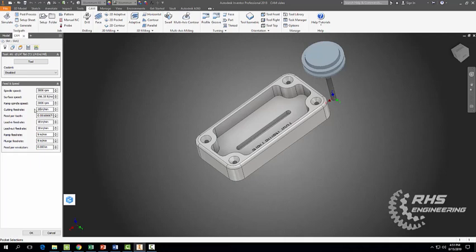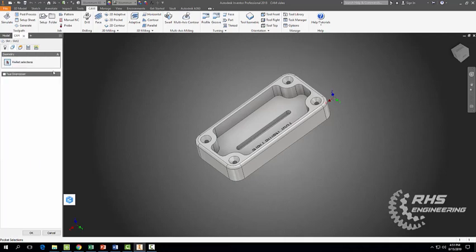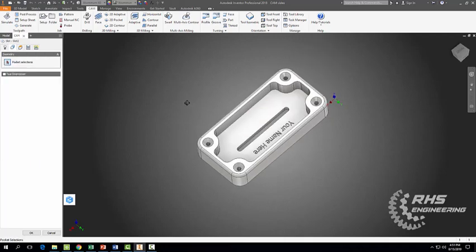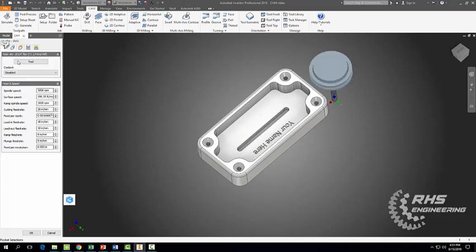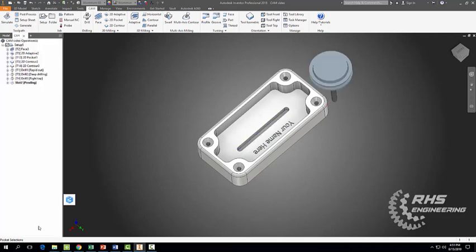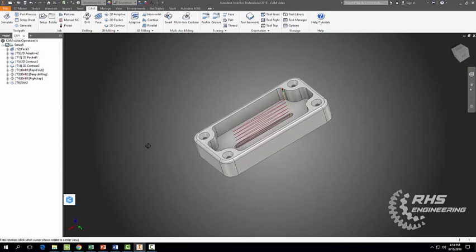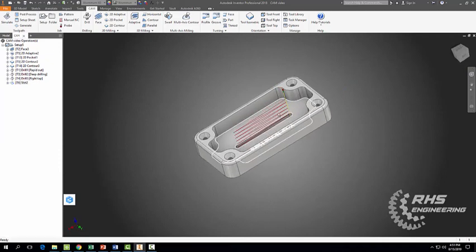Okay. Now let's come on over here to the geometry tab and we're going to select this linear portion here in the bottom. Okay. And that should do it. I can't remember. Cooling is disabled. Let's go ahead and hit OK. And there we go. There's our slot operation. So our mill's going to come down and remove the material right down through the middle here.